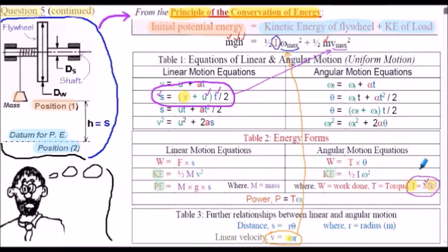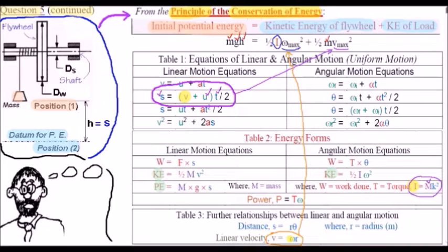So we need to transpose the energy balance to make I the subject of the equation. We can then solve for I. So the only value left to find will be the radius of gyration k. So quite a complicated thought process here to generate the energy balance and then decide what parameters we need to determine before we can solve the equation to find the radius of gyration.